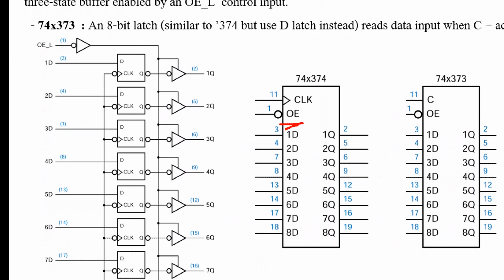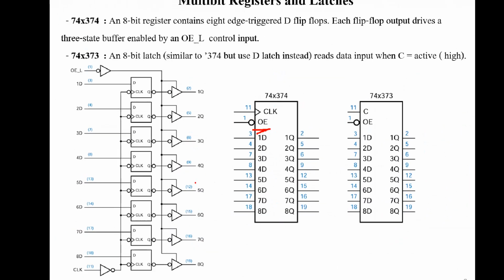Inside this IC, if you want to use the output, it should be logic low. Apply low here, 0 here, output is 1. And it's a 3-state buffer here. So it's 1, right? So the signal from input will go to the output. But when enable is not active, namely when you apply 1 here, it becomes 0 here, right?